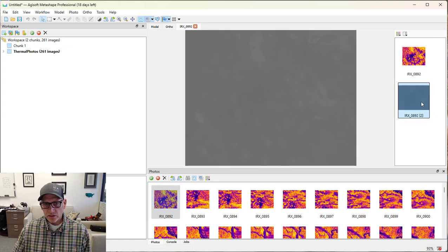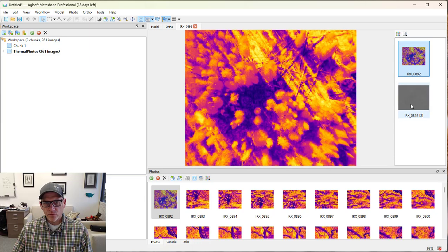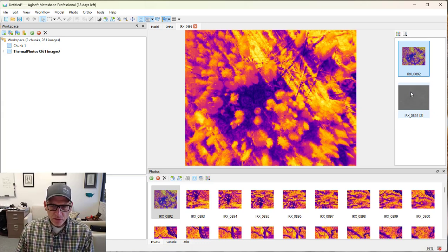And if I click on this one, the contrast of this image is not really great, but this is basically the same thing that we were seeing over in QGIS. So I could toggle back and forth between these. The thing to know here is that it's brought both the RGB version and the temperature data in, assigned as 2 layers to the same image.